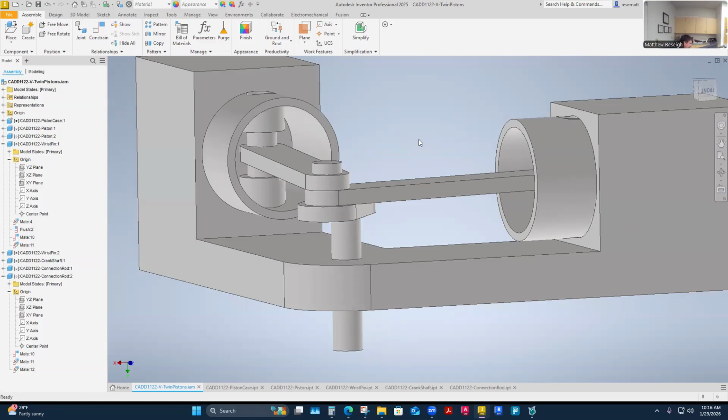So they have little thrust loading strength. These are really little ones, so they take a special tool to use. There are two little holes in them, and it takes a snap ring plier to open and close those.